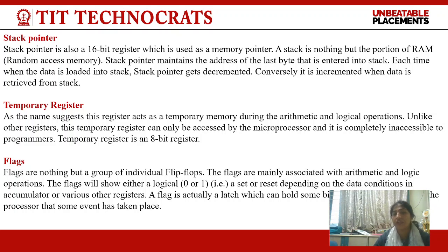The flags are mainly associated with arithmetic and logical operations. A flag will show either set or reset depending on the data condition in the accumulator and various other registers. A flag is actually a latch that can hold some bit of information, telling the processor that some event can take place.